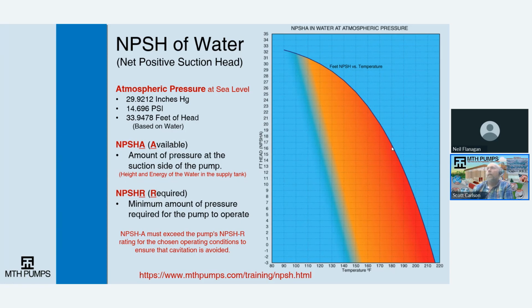And that's when you'll start seeing the effects on some of the large pumps. When you get all the way up to 200 degrees, then you're at 7 feet of NPSH. Then you'd really start feeling or seeing the pump have trouble keeping up, and it'll start to cavitate.